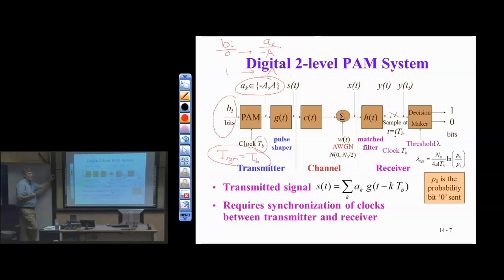I would have a hard time detecting that. Detection's a problem, because those rectangular pulses are so short. Also, bandwidth would be infinite. Remember, an impulse train in the time domain is an impulse train in the frequency domain, so it uses up all the bandwidth.